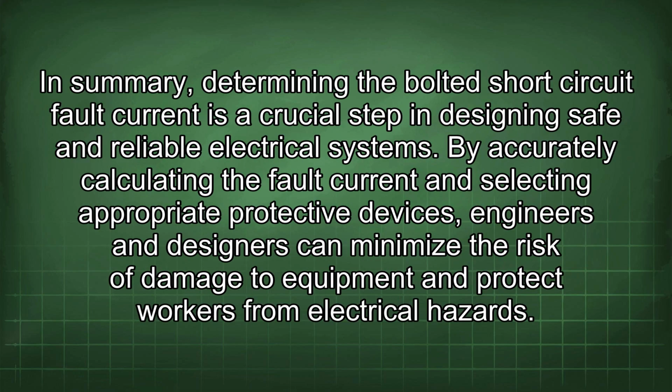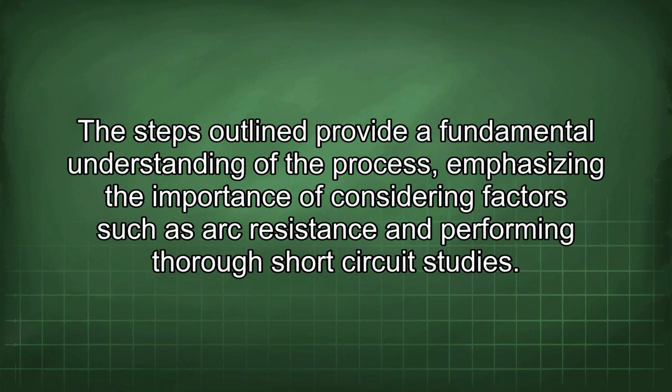In summary, determining the bolted short-circuit fault current is a crucial step in designing safe and reliable electrical systems. By accurately calculating the fault current and selecting appropriate protective devices, engineers and designers can minimize the risk of damage to equipment and protect workers from electrical hazards. The steps outlined provide a fundamental understanding of the process, emphasizing the importance of considering factors such as arc resistance and performing thorough short-circuit studies.